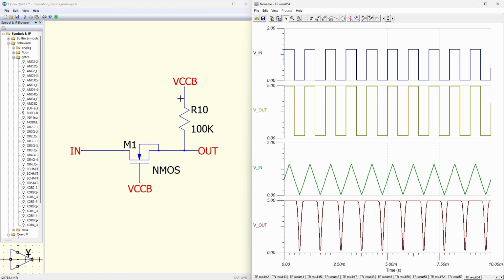You can improve this by reducing this resistor value, but the more you reduce this resistor, the more current will have to sink into your input device. So there's going to be a balance between how much drive strength your input device is able to handle and how fast your output needs to be. And the fact is that many times this circuit won't work very well for high-speed signals. You'll most likely have to go to a dual supply translator, which will be the last one we look at.